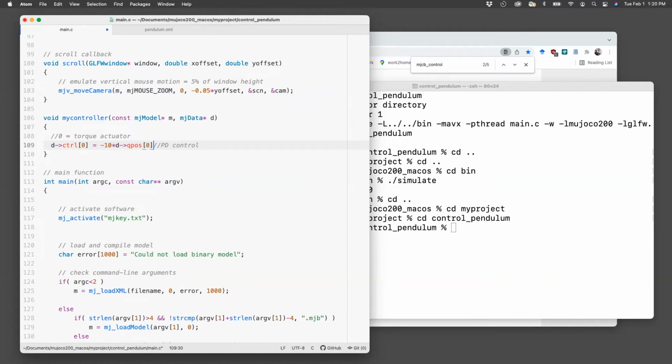Okay, so that's what we want. That minus 0, our set point is 0. If you want something else, you can put that minus kV, the velocity gain, times the velocity. So Q vel 0. Okay, that's it.